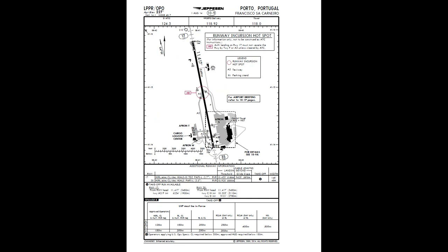particular route. And now if we go to the airport chart, we will leave the apron via Foxtrot, then we will enter into holding point Foxtrot, backtrack the runway to the end of runway 17, 180 degree to the backtrack, and then take off on runway direction 173 degree, as you can see here. The airport elevation is 227 feet, and we expect a takeoff run available of around 11,417 feet, or around 3.5 kilometers. LVP are in force. Actually, we have an RVR of 400 meters, so that's pretty fine.